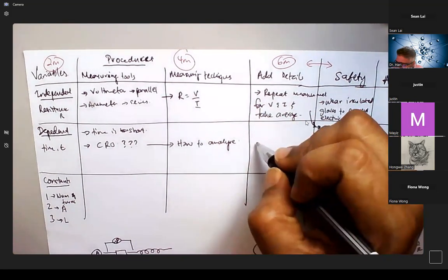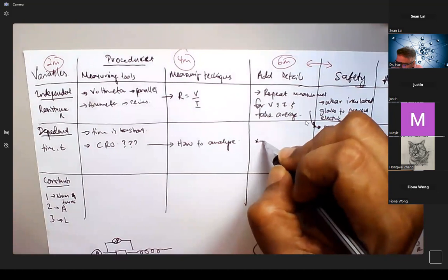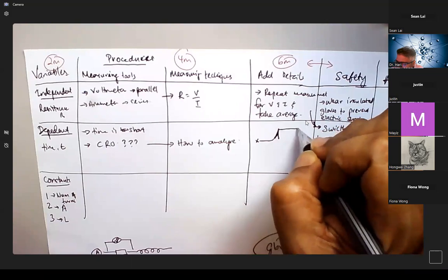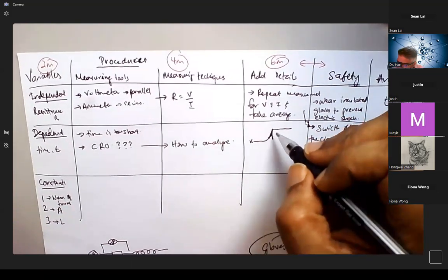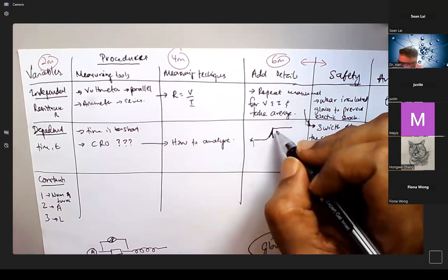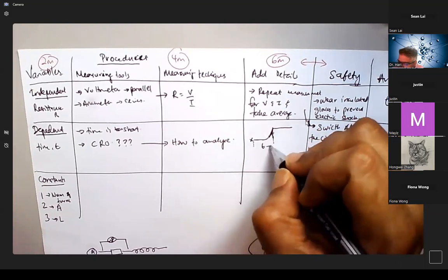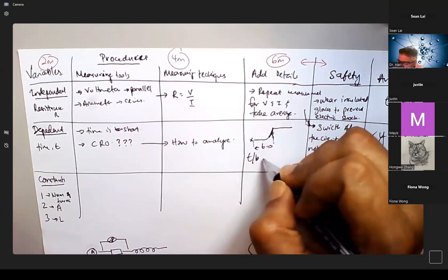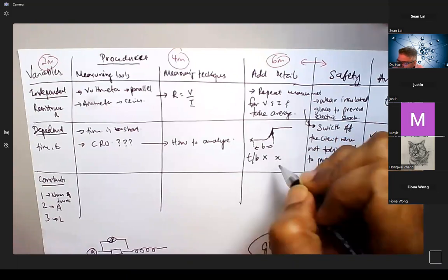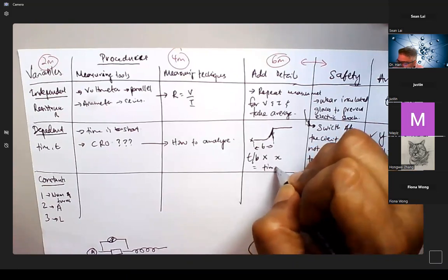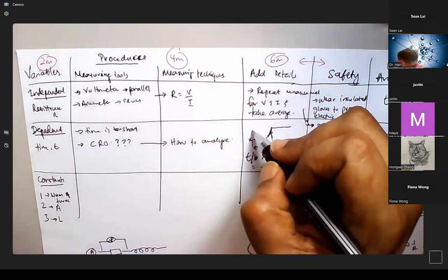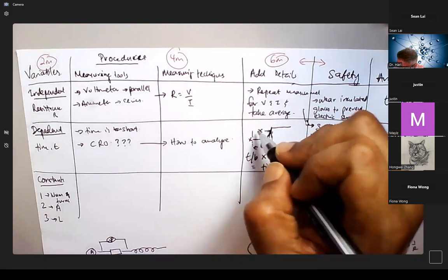Let's say you start at this point and then the value goes up. The resistance goes up. So you're finding the time, right? Maybe the point you start and the point you're taking the reading, and then the time base times X, you get the time. It's the setting of the time base times how long it takes to get the particular reading.